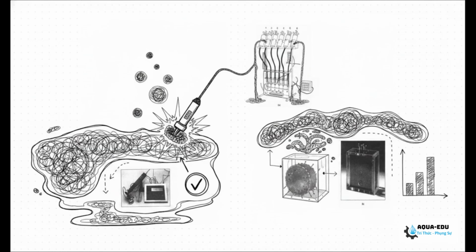Remember, an oil layer suffocates everything it touches. You must physically wipe down those DO sensors and recalibrate them. After that, check the biological respiration using a respirometer if you've got one handy. We desperately need to know just how badly our bacteria are struggling to breathe under that heavy lipid coating.